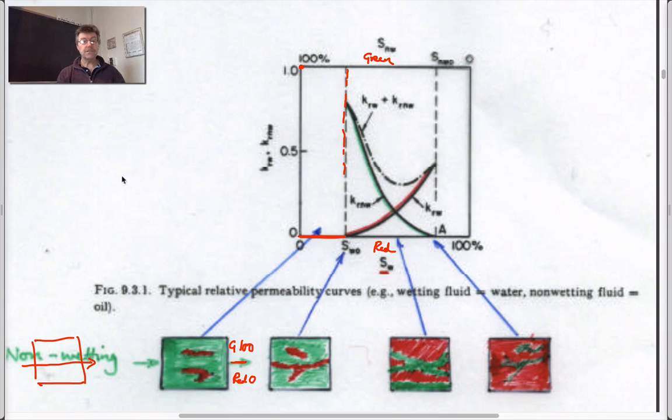So in other words, if you're sitting at the bottom on this capillary barrier with this little puddle that you're sucking stuff out of, if you have a borehole that goes into this, then you're basically in this regime here, and you'll be sucking out the DNAPL. Great. You'll be able to take it out. As you physically remove the DNAPL, as this area shrinks, it's going to have to suck in water from around it, because it has to substitute the removed volume.